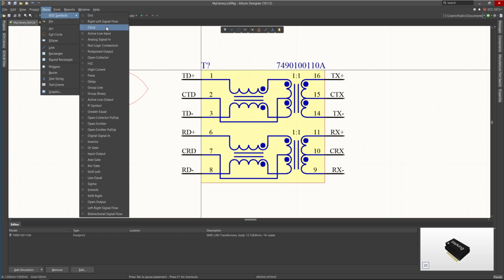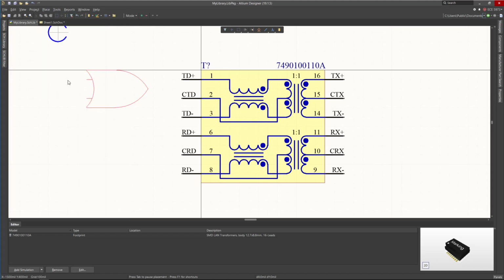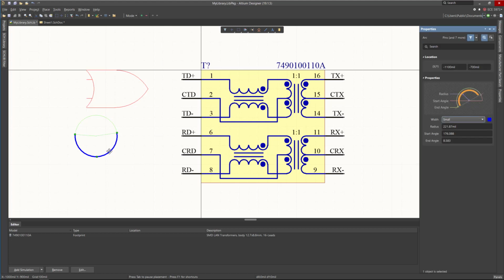And if the symbol is not among these, you can create that symbol. So you have arcs. Whenever you click, so this is an arc for instance, double click, escape, you will edit it. Now you can change the arc as well. And if you want to control the color and the properties of that, basically double click on it and the properties will come up in here.